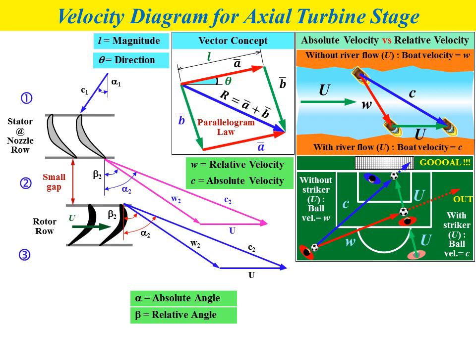And at the outlet of the rotor, at condition number 3, we have the relative velocity vector of the rotor, w3, and its direction depends on the shape of the rotor blades. Because the rotor involves a blade speed vector, we need to add w3, the relative velocity at the outlet of the rotor, plus the blade speed vector u.